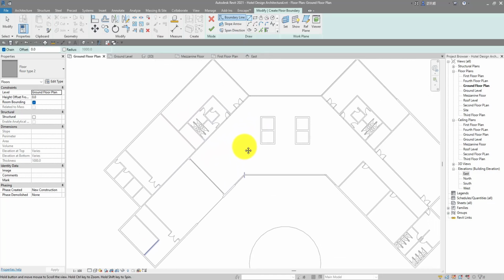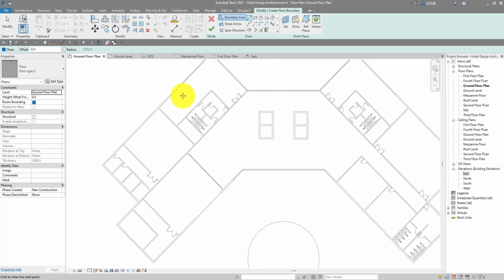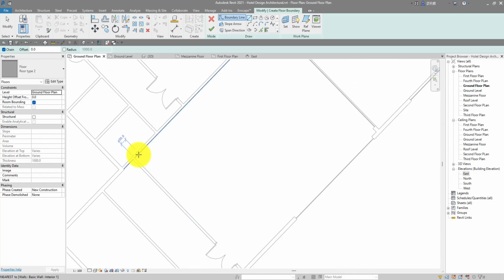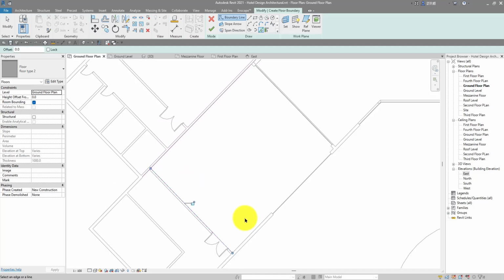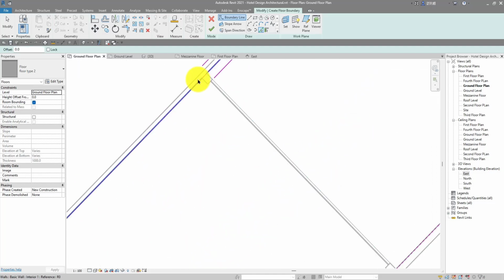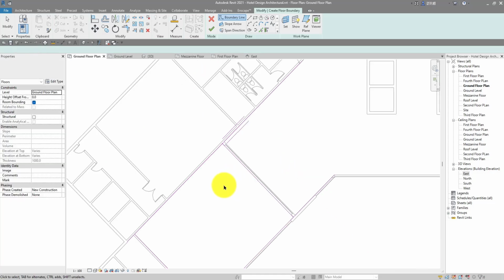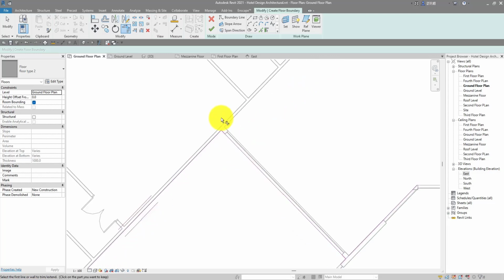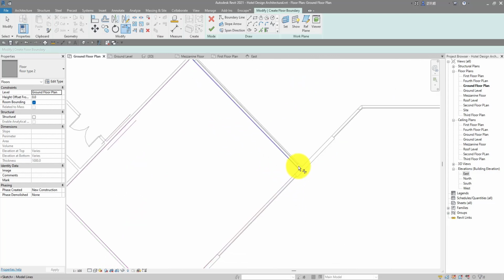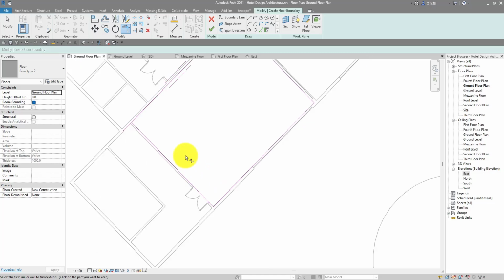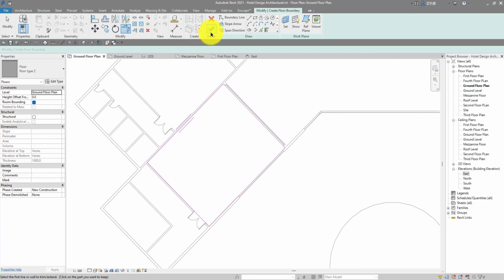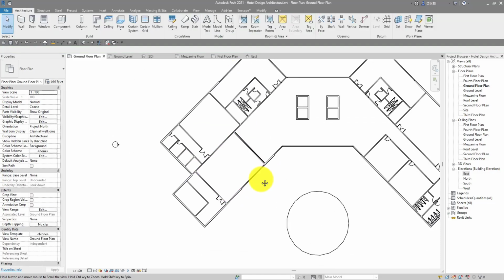So our floor type 3 was for this area. Okay, so we are going to use the same floor type 2. So I'm going to use the pick line. Just select this and select this, select this, select this. Escape key a couple of times, TR on your keyboard, and then you just trim this with this, trim this with that, and also trim this with this, and trim this with that as well. Hit on the finish. We have that in there.